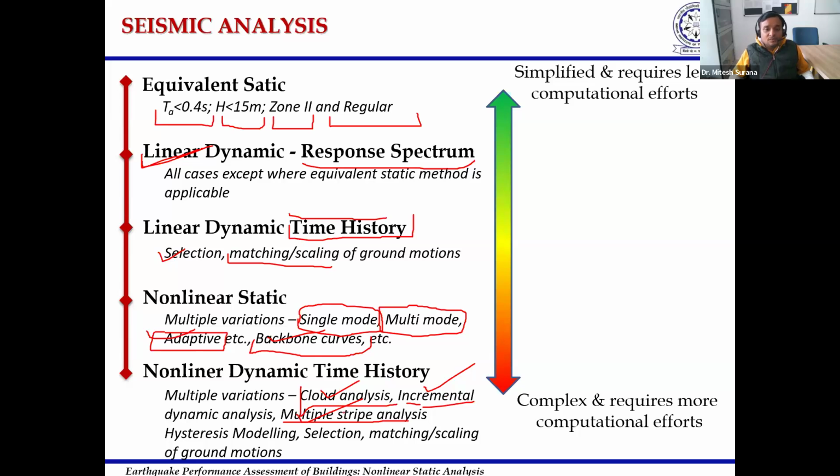Then apart from this, when we are performing nonlinear dynamic time history analysis, we are analyzing the structure actually during the structure being subjected to earthquake loads. Therefore, we need to incorporate the member force displacement relationship appropriately by choosing the appropriate hysteresis model that takes into account the effect of cyclic loading, reverse cyclic loading that occurs during an earthquake, and how the material or the member will degrade with continuously increasing displacement cycles over time. So that effect also we need to incorporate in our analysis model.